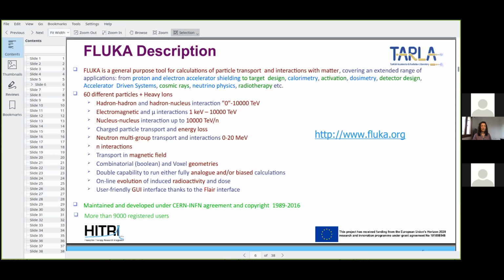For most applications in nuclear physics and radiation physics, you wouldn't be dealing with such high energies. Something up to a GeV is all you will reach, so some of the more hypothetical particles will be out of the question. The second part is this matter interaction, where you're simulating detectors or shielding issues and similar. Issues like neutron transport are of very high importance. For applications in medical physics, one advantage of FLUKA is its ability to deal with voxel geometries, and there are even ways to import geometries directly from PET cameras or similar diagnostic devices.